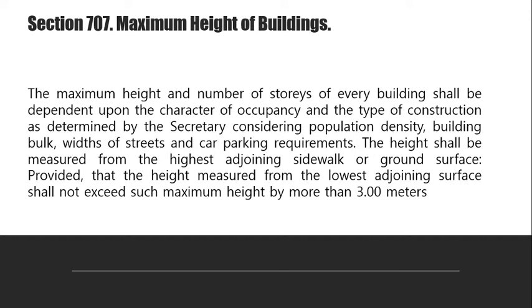So remember this, not to exceed 6 meters above the height limits for each occupancy group if of combustible materials.